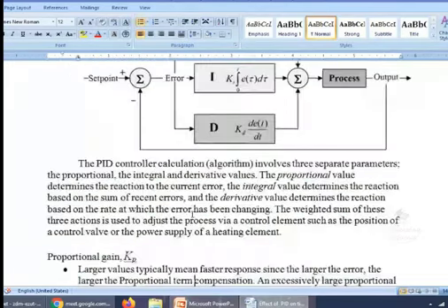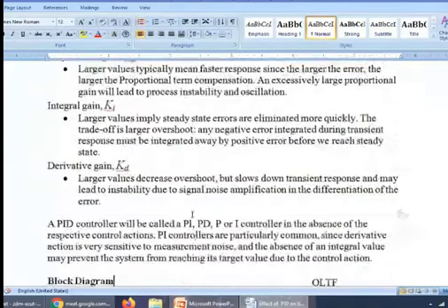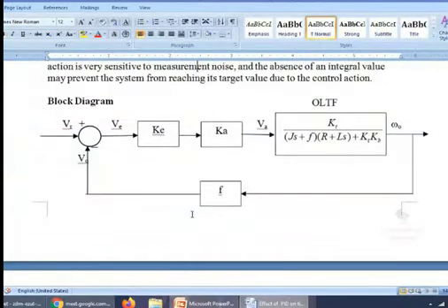The PD controller mode is for your knowledge. What is the response I am getting? That is what we emphasize here. My transfer function is KT divided by (JS plus F) into (R plus LS) plus KB into KD. This is the system I have chosen. In my laboratory, I have chosen this as a DC servo motor, but it may be any system. So K is my error gain and K is my amplifier gain. This is my open loop transfer function.